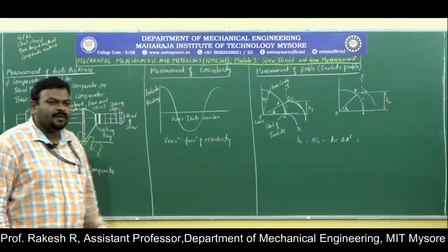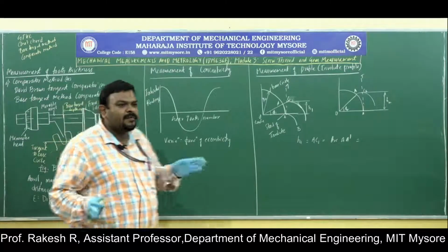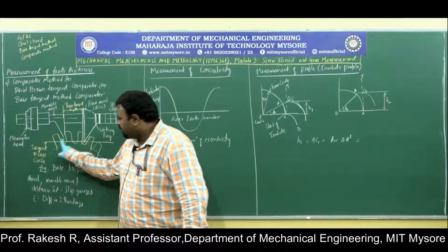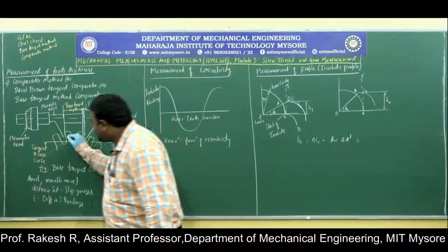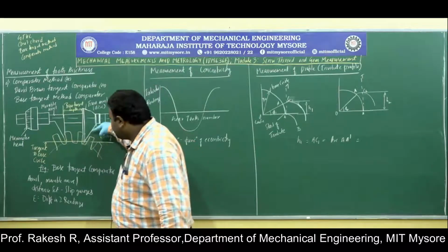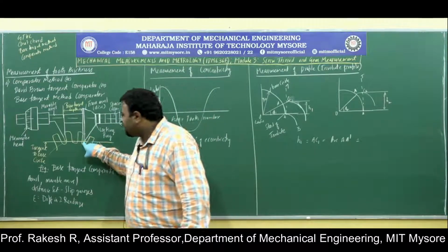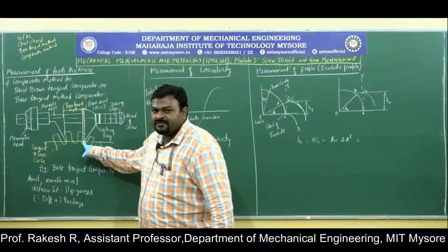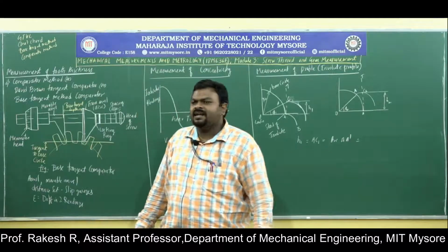So let us see what the operator setup is. Simply there are two things. One is a fixed anvil, another one is a movable anvil. So you will be adjusting like a tangent. So this is a base circle. In the base circle you will be drawing a tangent. It is a base tangent, and you will be adjusting these things, the movable and fixed anvil, towards the tangent. The teeth will touch and be in contact up to the tangent point. So there is a contact of the fixed anvil, here there is a contact of the movable anvil, and there is an